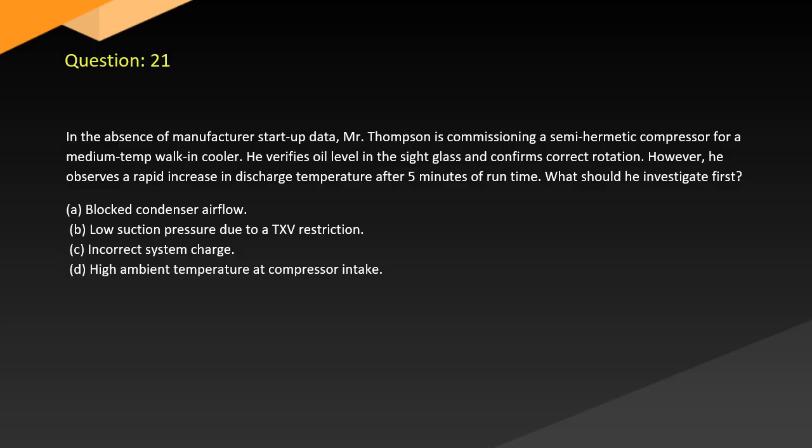Question 21. In the absence of manufacturer startup data, Mr. Thompson is commissioning a semi-hermetic compressor for a medium-temp walk-in cooler. He verifies oil level in the site glass and confirms correct rotation. However, he observes a rapid increase in discharge temperature after 5 minutes of run time. What should he investigate first? A. Blocked condenser airflow. B. Low suction pressure due to an EXV restriction. C. Incorrect system charge. D. High ambient temperature at compressor intake.